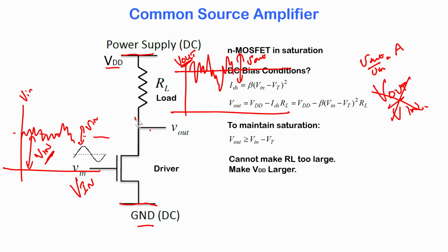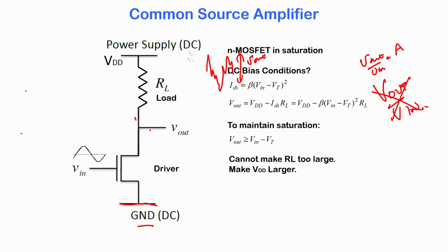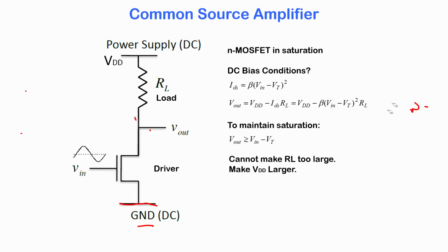So, we are only illustrating this fluctuation, we have ignored all this, we are only interested in the small signal fluctuations of the MOSFET. Okay. So, we can draw two different circuits. If AC and DC are all happening together, it would be too confusing to analyze both of them together. So, what we will say is from this point on, whenever we do AC analysis, we will ground all DC points.